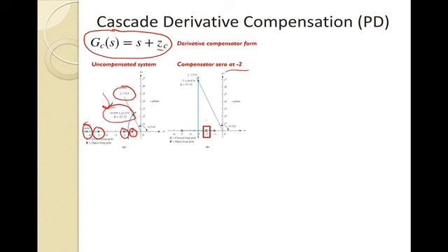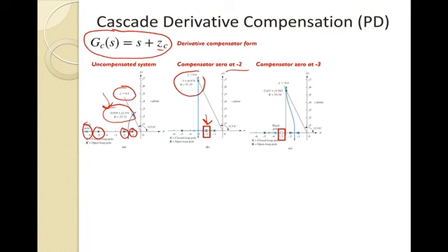Now, why would we do that? You can see that right there. Well, that compensator zero at -2 is essentially going after this pole, and we see if we could have essentially a pole-zero cancellation. Also, if we wanted to maintain that damping, you can see an increased value of K from 23.7 to roughly 51.25.